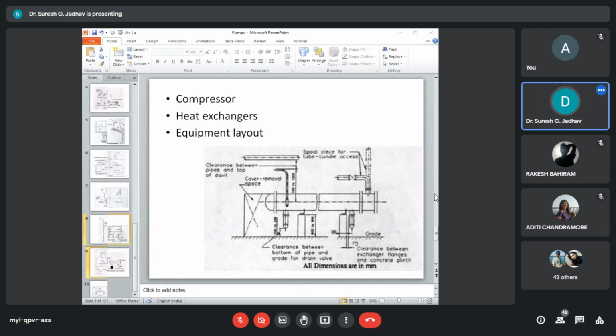Manufacturer's recommendation should be followed in this case. The reciprocating compressors are located on a concrete foundation at grade level and not a concrete tabletop. The basis of a laydown area, foundation, and the roof above are identical to that of centrifugal machines. The piping interconnecting the pulsation dampers, intercoolers, and aftercoolers should be short and simple to reduce the vibrations.